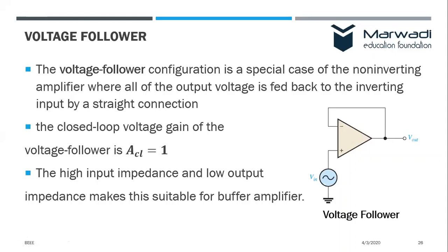My heartbeat is a very weak signal, so it may not be able to provide 10 milliampere to the output, right? If that is not possible, then we use the voltage follower circuit.